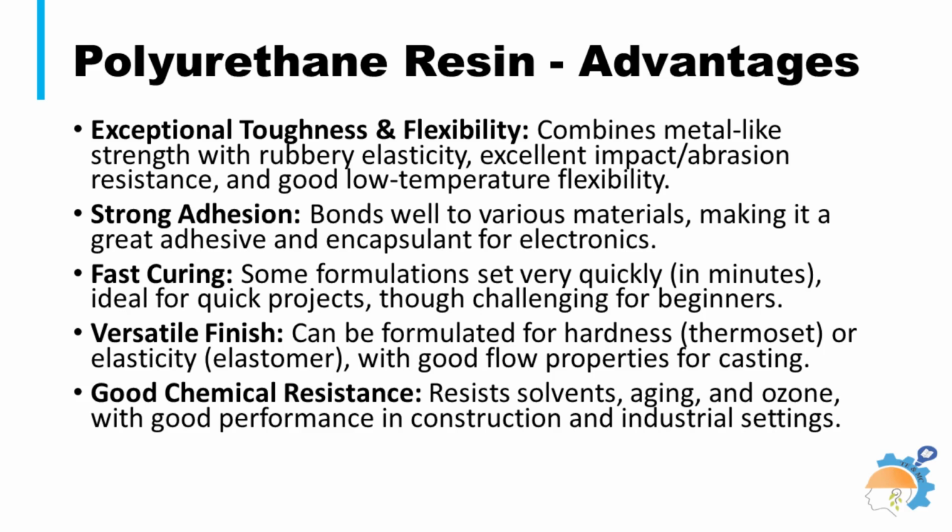Polyurethane, PU, resin offers great toughness, flexibility, abrasion resistance, and strong adhesion, making it versatile for coatings, adhesives, and casting. It combines rubbery elasticity with metallic strength. These are applied in pultrusion, RTM, and reaction injection molding, also called RIM.